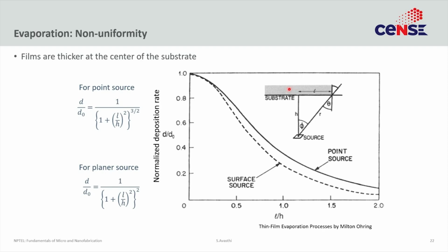All right. But then there is more to that. In the previous figure we were talking about wafer to wafer non-uniformity. But within the wafer itself, the wafer is not a curved piece, the wafer is a flat piece. So if the wafer is a flat piece, the angle of impingement of the incoming flux at the center is very different from the angle at the edge. So there would be some theta dependence across the flat region of the wafer.